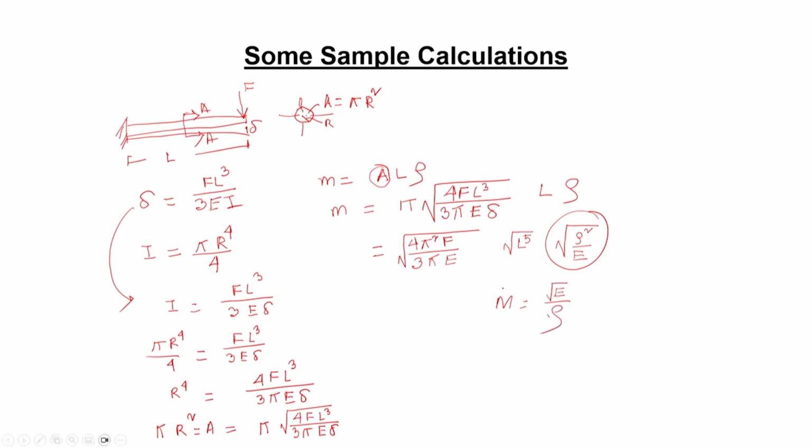So, that becomes our material property index corresponding to the light cantilever beam, which means very simply that if I want to reduce the mass of my aircraft wing, then from the material point of view, I have to reduce square root of rho square over E, which is equivalent to the increase of, look, this is capital M, okay, do not confuse it with the small m, the increase of the material property index, and such that square root of E over rho is actually maximized.